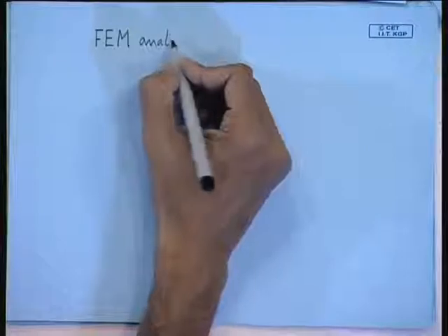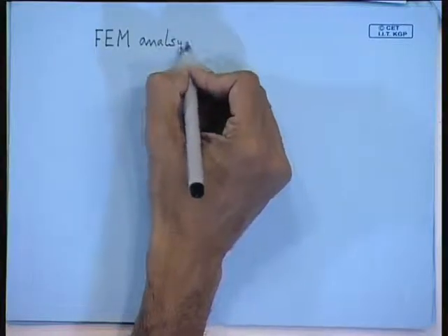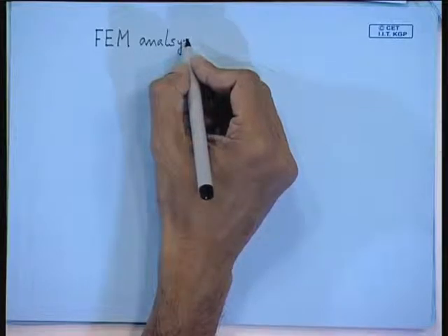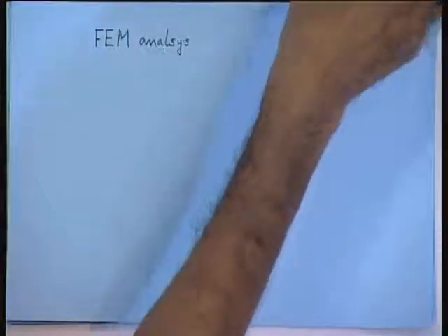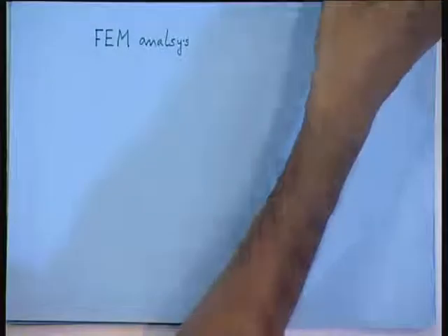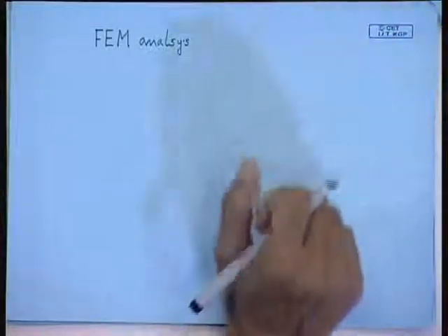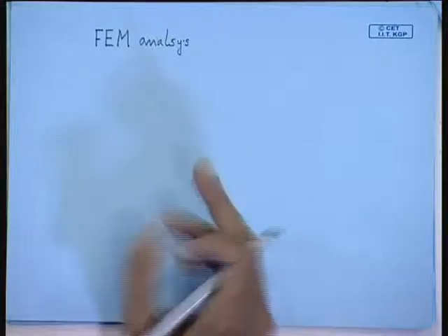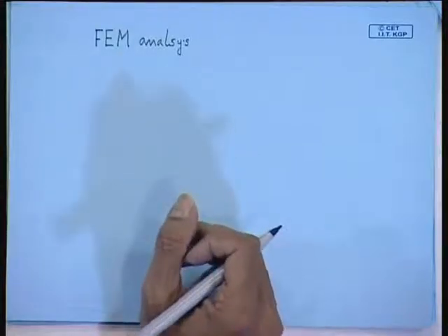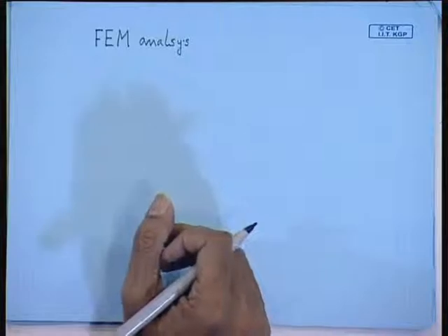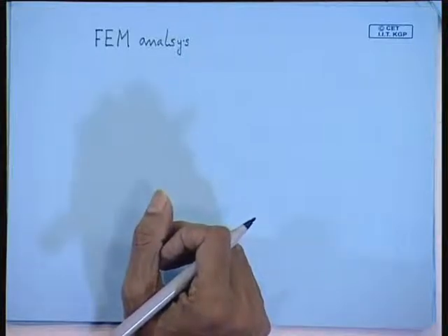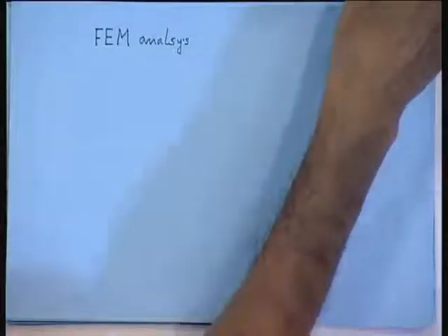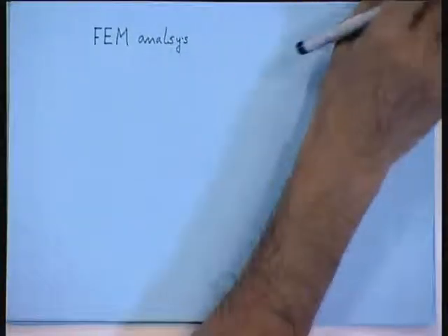Now this FEM analysis is also not very simple, because in this we have assumed that there are no hydrodynamic forces acting on the cable line. That means we have vanished the F and D terms. You remember at the beginning when we started simplifying. So that is also a very dangerous assumption, but since this is a simplified case, we are saying that that is equal to 0,